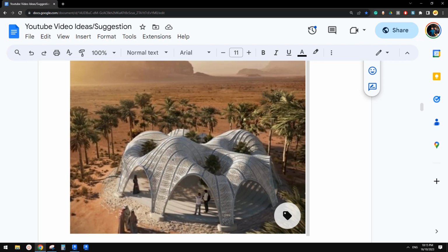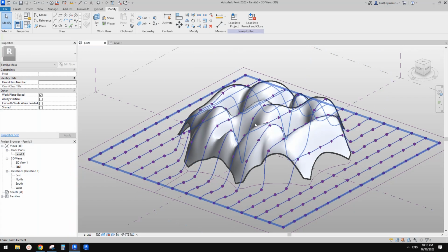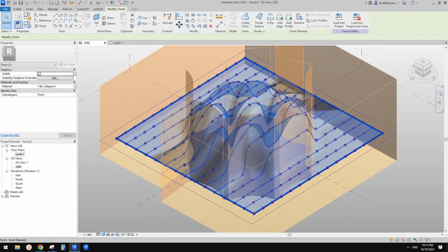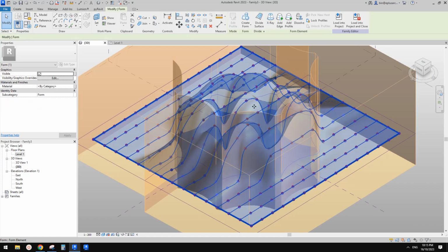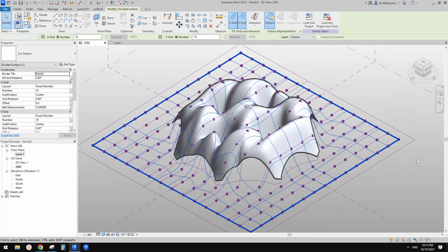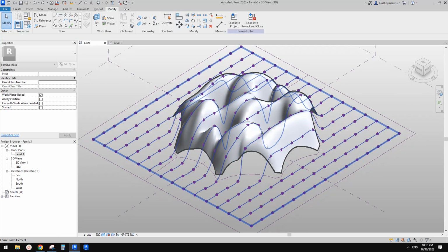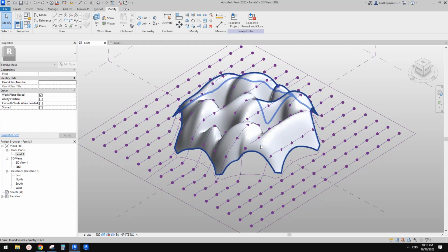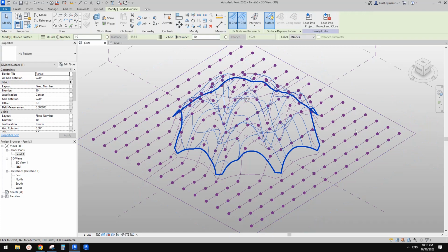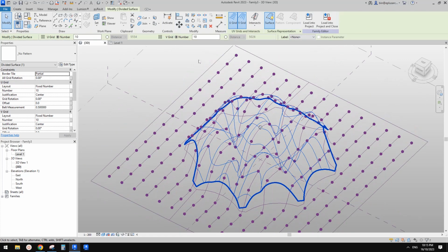this, what do we call this? You can always use a divided surface or adaptive family. So you can use divided surface. Oops, sorry, Control Z. You need to tab twice, and then use divided surface. Okay, and then it's hard to see.